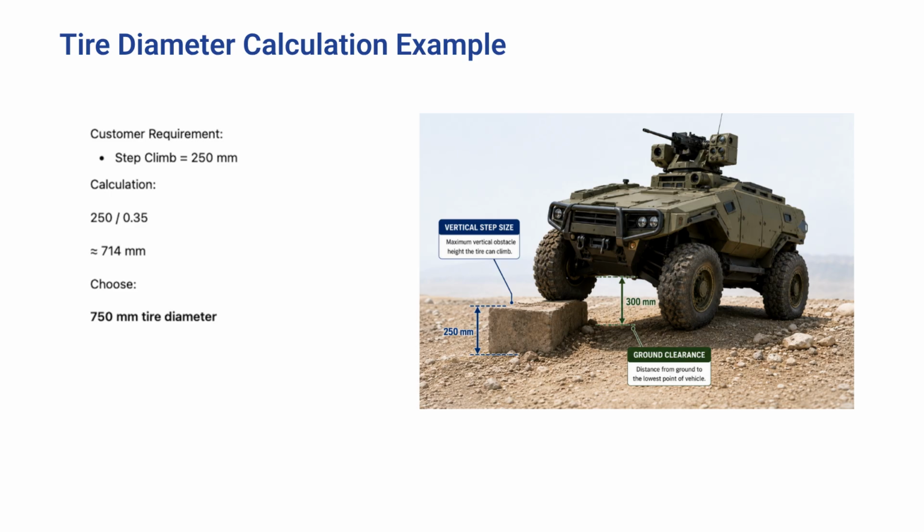ISO 612 defines ground clearance as a vehicle dimension measured vertically from the supporting ground plane to the lowest fixed point beneath the vehicle. The vehicle should be positioned on level ground and the measurement must be taken to an underbody component, not to the tyre or wheel. This gives engineers a consistent method for comparing vehicle clearance.